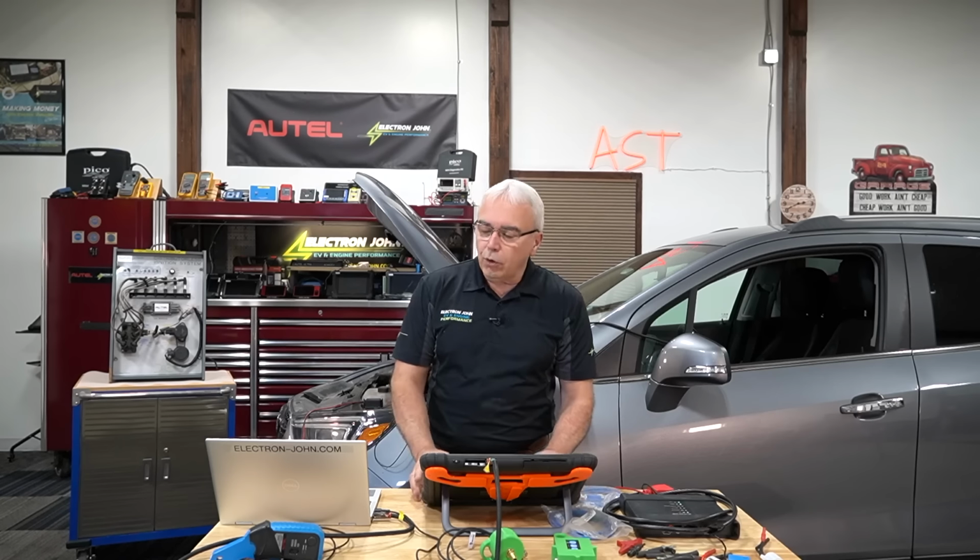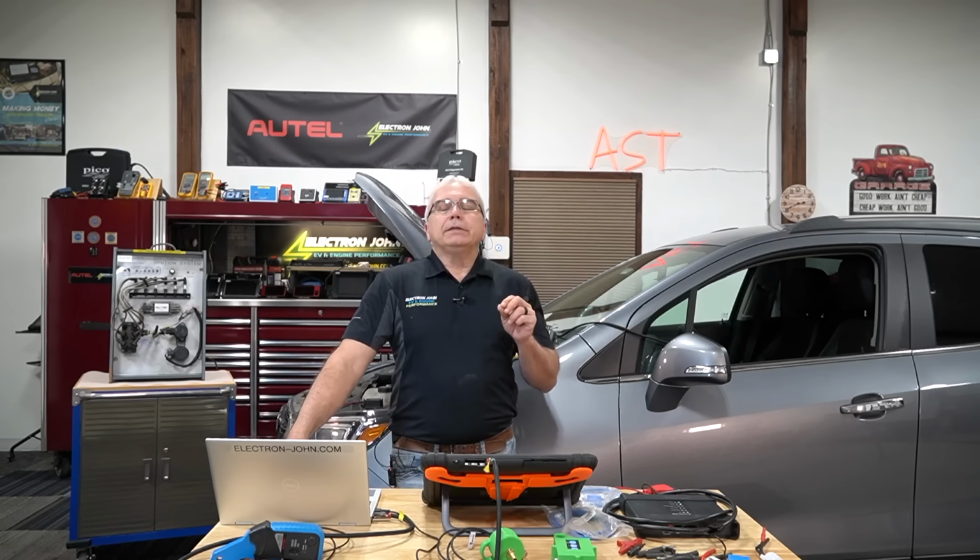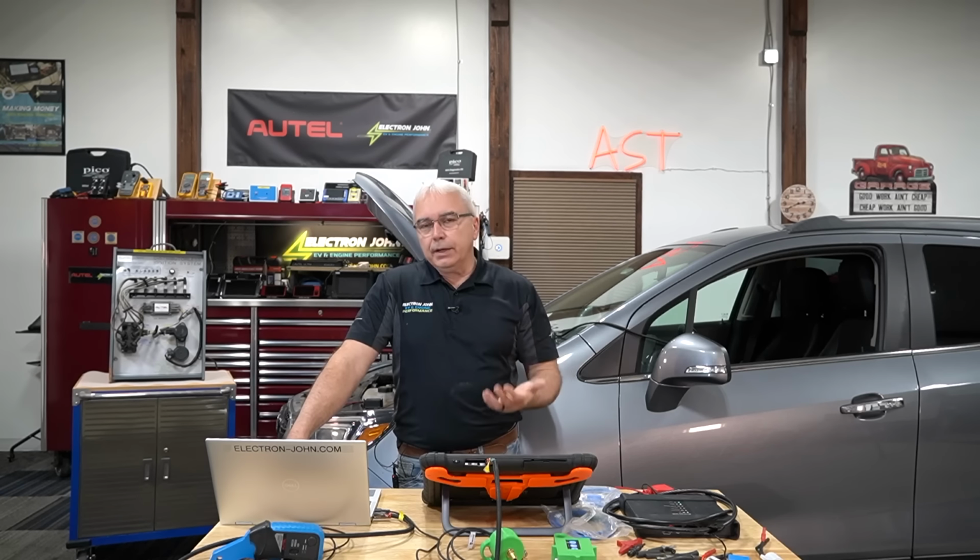So with the scope, if it's got an engine breathing type of problem, well, what could cause that, right? So I could open the hood. If I determine I had a mechanical problem, I could open the hood on the car, and like we said before, start off by doing a manual compression test, then go into a cylinder leakage test.